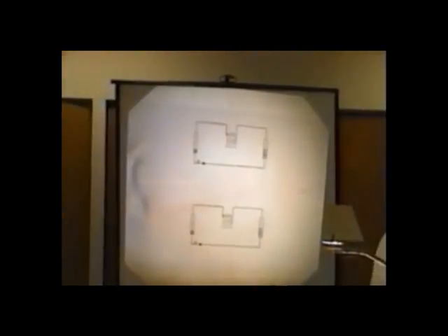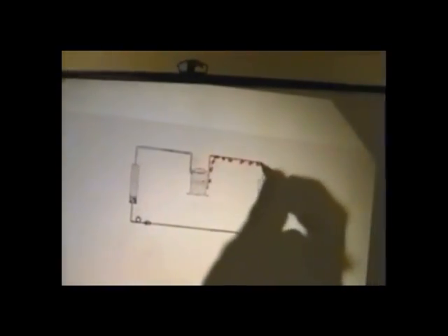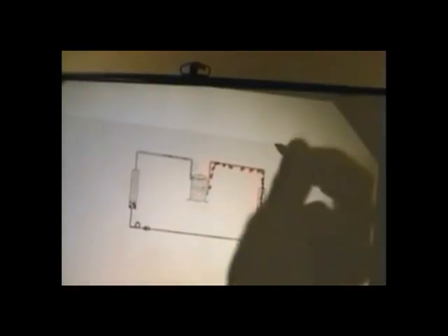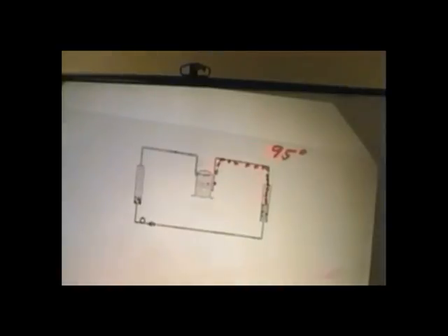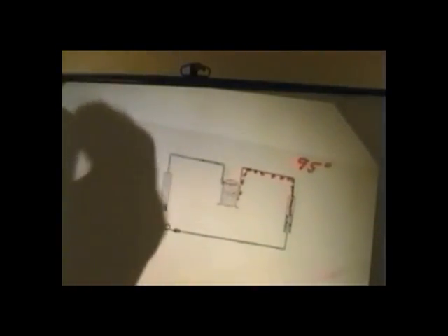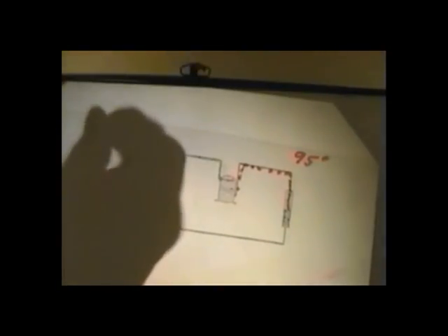We're going to go clockwise. It doesn't make any difference which way we go, clockwise or counterclockwise, but that's a compressor. And with the compressor, we are pumping heat-laden vapor into the condenser. And by the way, we're going to talk about a 95-degree ambient temperature outside. How's that? And this central air conditioner, we can call it a 3-ton, is doing so good that the inside of the house is 75 degrees, nice and cool and dry. It's working great.